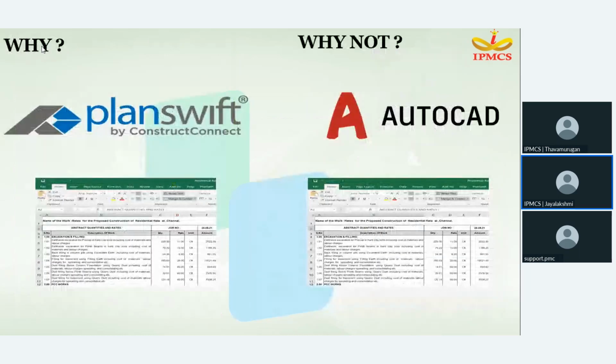So why PlanSwift and Excel? Why not AutoCAD and Excel? When we think about PlanSwift and Excel, there is a live linking between PlanSwift and Excel. So any measurement revision in the drawing will be automatically reflected in the connected cell. If a new item is added or deleted, it can be easily identified using the overlays option inside PlanSwift.